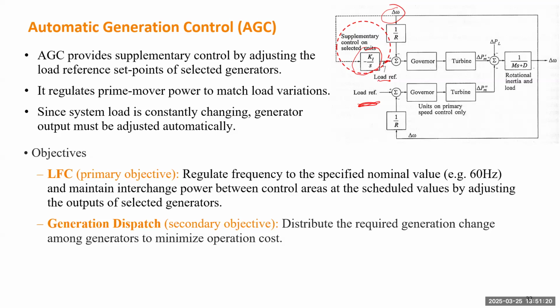But when the system is experiencing some disturbance or new conditions, if you have multiple units connected to the AGC, you can first bring the frequency back to 60 Hertz, so that you can recover back to the dispatch result. And you can also use the AGC to influence some of the units, which can help to reduce the operation cost. So that can give you more flexibility.